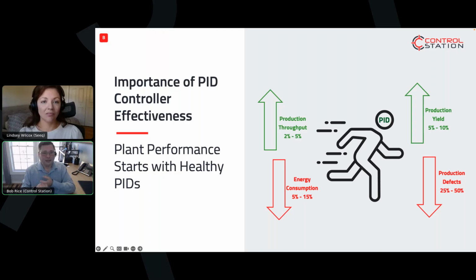I did a project probably 10 years ago at a refinery. We just did optimization on all the utility loops. So anything that used cooling or anything that used steam, we went through and tuned all the heat exchangers. Whatever the variance that we removed, we may have removed 1 or 2 degrees, then we moved the set point up 1 or 2 degrees.